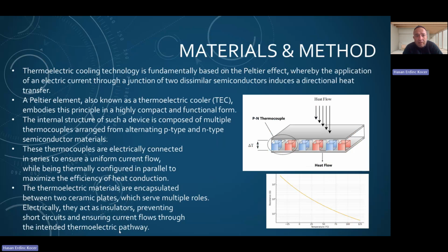These thermocouples are electrically connected in series to ensure a uniform current flow. The materials are encapsulated between two ceramic plates, which act as electrical insulators, preventing short circuits. The resistance and temperature graphic is shown below, as you can see.